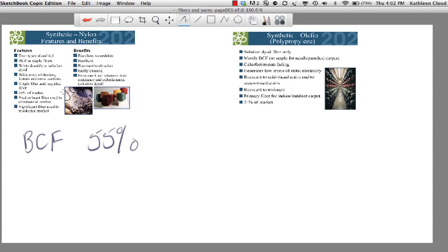Solution dyed nylon has excellent color fastness to light and crocking, atmospheric contaminants, and harsh cleaning chemicals, in addition to excellent color clarity. It is also offered by some manufacturers with inherent stain-resistant properties, providing excellent resistance to acid-based stains that can often be removed simply with water.